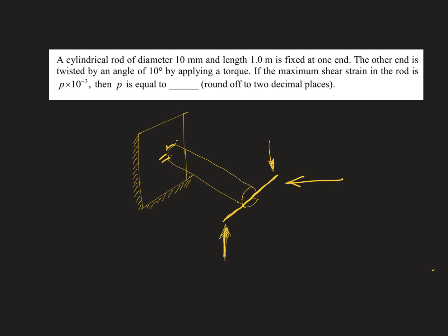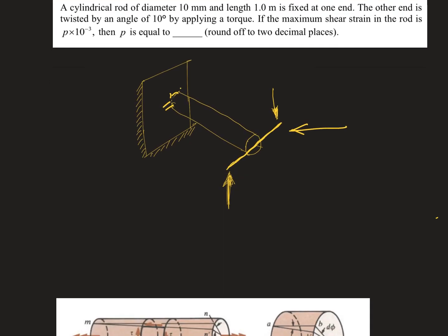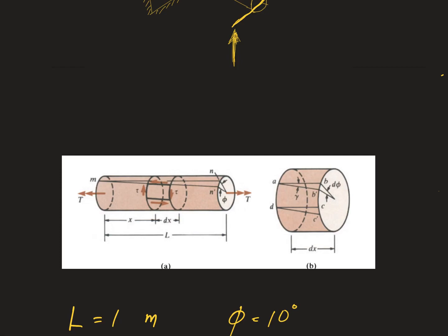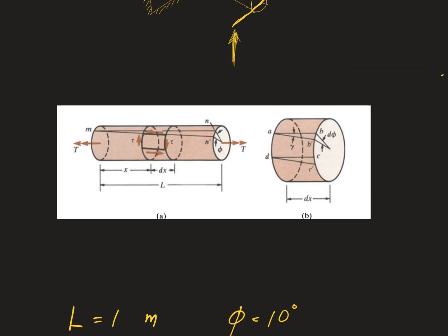It's a very interesting problem because I think this is one of those concepts which usually students overlook when reading or when learning about torsion. So here you see this is a bar subjected to torsion, pure torsion. This particular double arrow symbol is usually used to denote the torque acting at a particular point. Then what happens to this small dx element, delta element? It undergoes shear.